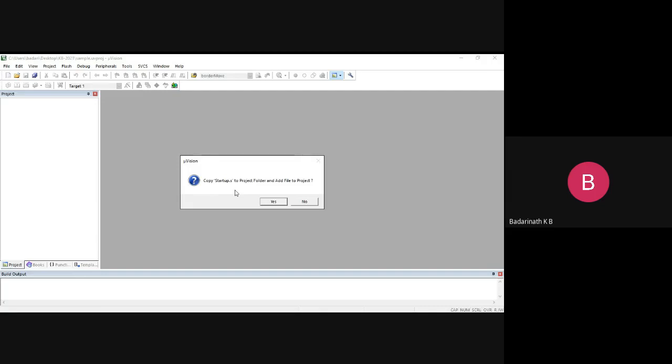code for this microcontroller. In the sense, whenever you boot, whenever you start the microcontroller which you used in your project for which you are developing software, automatically this startup code will be executed and initialize the basic things required for this microcontroller. Because every microcontroller, when you start, you have to do certain housekeeping things that either you have to write a code for, or a ready file is available from the supplier of that microcontroller. You can use that one.